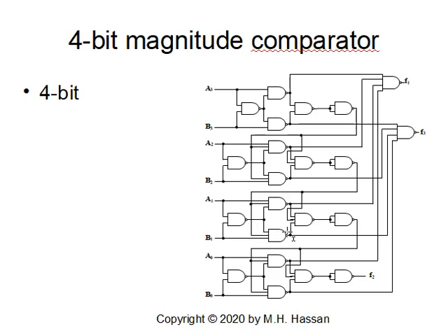If this is 1, we feed it back here, and this has to be 1. We feed it back to the last sequence, and the output F2 will be 1 here with the test of the two least significant bits, which are A0, B0. So this is the sequence. We prove that F23 is 1, F22 is 1, F21 is 1, and F20 is 1. And by ANDing all these, we get F2. So this circuit is fully verified.